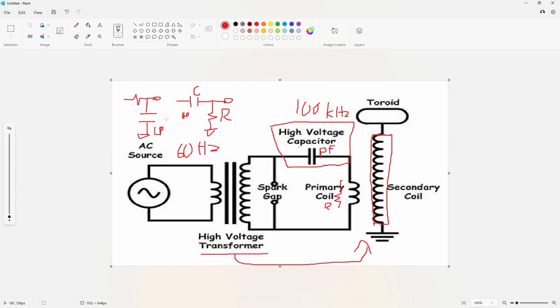The important component in your high pass or low pass filter, in a crude model, is really the capacitor. It's not the resistor. If you just put a resistor there, you're not going to get any different frequency response. Depending on the value of the resistor, you're just going to change some of your voltage orientation at a certain node in the circuit, but you're not going to get a frequency response change. What's responsible for the frequency response change is the capacitor and the orientation of it. So this is the low pass filter, this is the high pass filter.